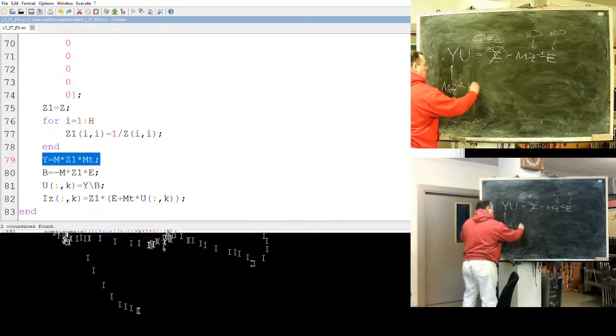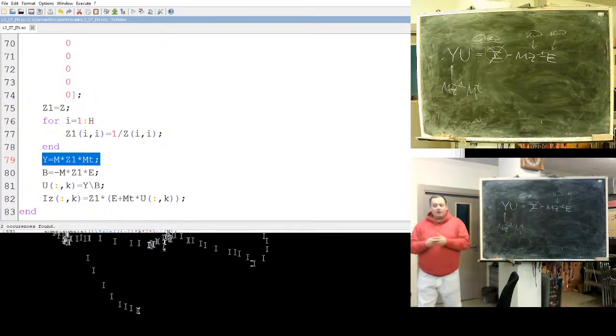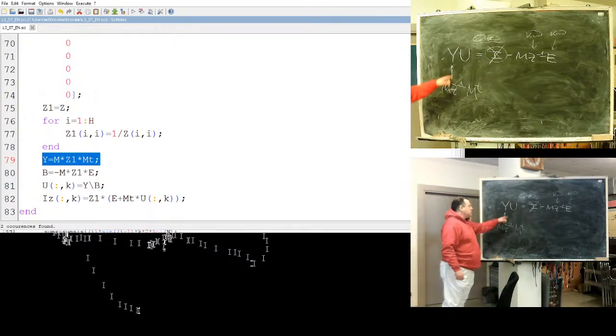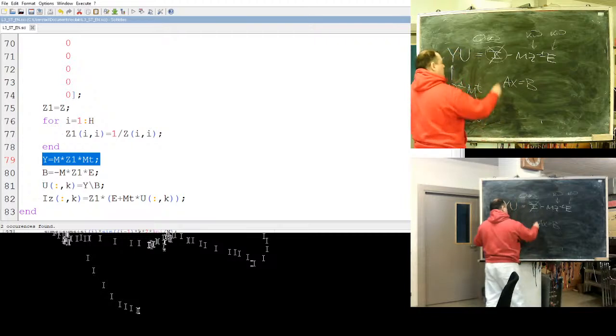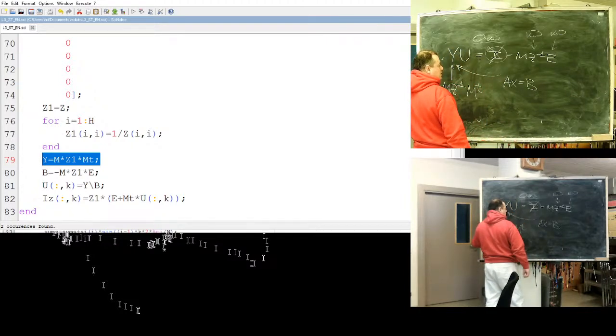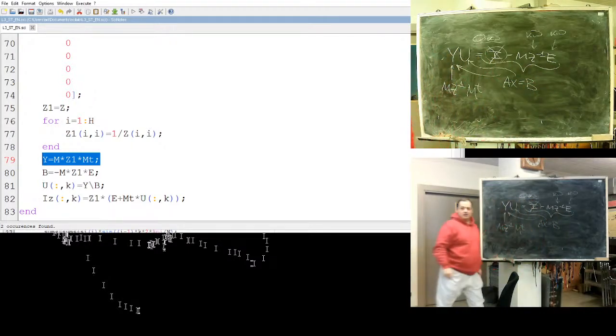And what is M? What is M? First, the incidence matrix, branch nodes, connection. In general, it's a linear system of linear equations: nodal conductance matrix, node voltages, and three elements, currents and EMFs. Professor, what is that called again? Nodal voltages, nodal voltages or current? Voltage. We solve with the aim to get node voltages.